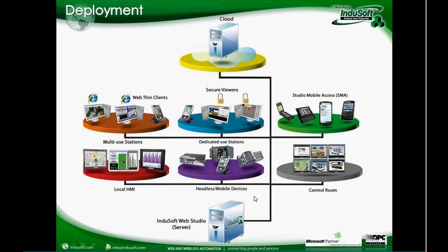You can download the application to local HMIs on the plant floor, or to computers in the control room, or to embedded devices or mobile devices, mobile controllers running Windows CE or Windows Embedded Operating System. In many cases, some blind devices that do not even provide a local display, a local HMI, are running the Studio software, collecting data from the devices and saving data to databases.